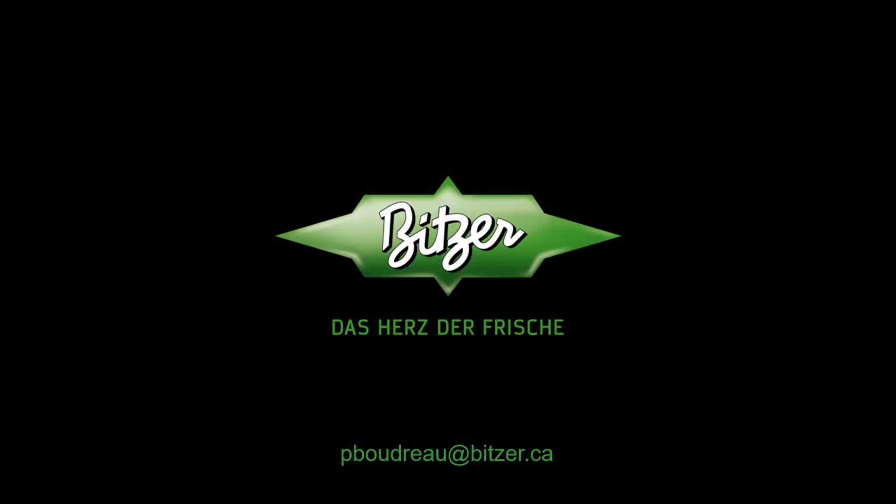Thank you so much. Another oil-related question from Mark Andre. Should we err on the side of higher viscosity oil if multiple options are available? We should actually look at the application in the operating instructions. For the compressor, it will suggest which oil to use based on the application. Generally the lower the temperature application, the lower the viscosity you would use. So you would look at what that temperature range is and choose the oil that's applicable.